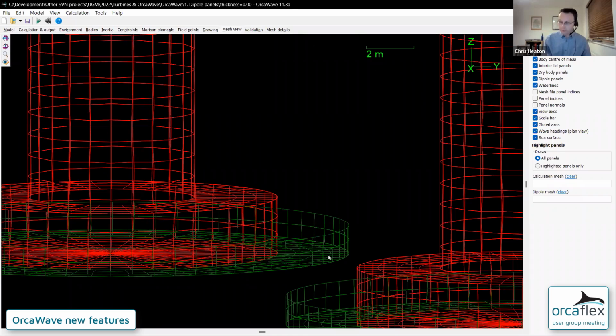And if I run this OrcaWave model, then the radiation and the diffraction effects of those thin parts of the structure are fully captured in the diffraction calculation, and their influence on the wave field. Physically, what we're modeling here is a pressure difference between the water on the two sides: the water above and below the heave plate and the water inside and outside this vertical skirt.